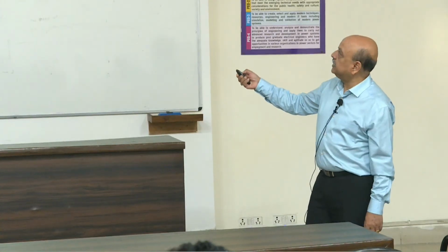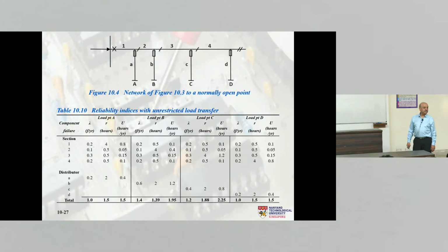No, if there is a fault here, this breaker will trip, right? Yeah, the breaker will trip, but supply will be disrupted. Yeah, supply is disrupted here, yes. And next you have told me we will put the various changes so that you can coordinate further. Yeah, so we are feeding it from here.